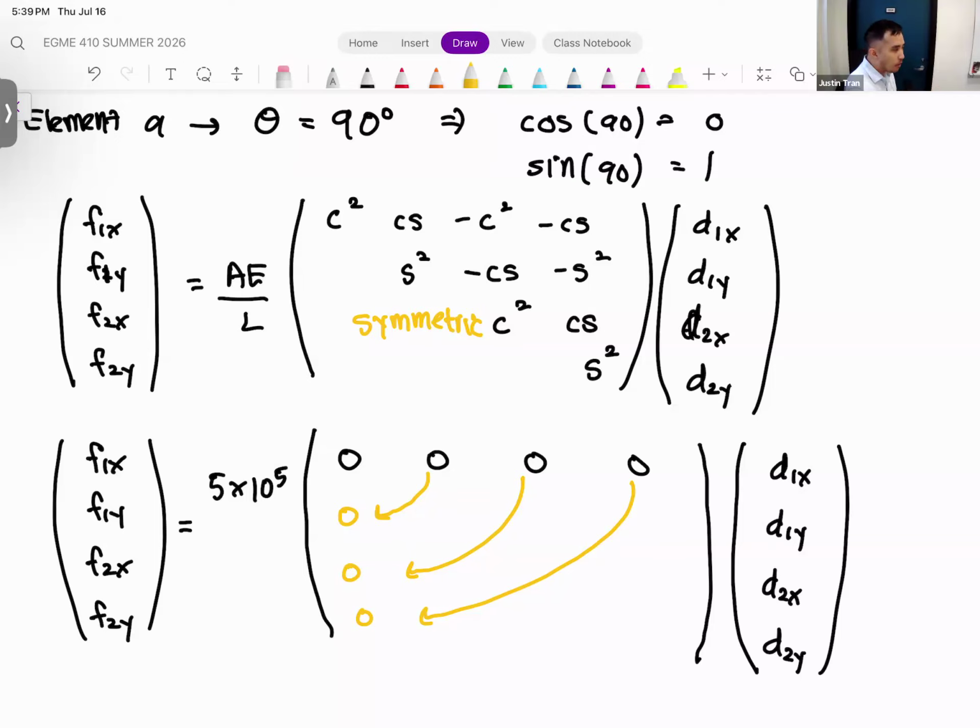And so that's a big part of the section, recognizing that, yes, there is a lot of writing that has to be done. These matrices are ginormous, but whatever shortcuts and whatever tricks that you can use to make sure that you're consistent in all your calculations, take advantage of everything, okay? And so one of them is taking advantage of the symmetry of our element stiffness matrix. Every time you write a row, you just write that into the column as well, okay? So row, column, okay?